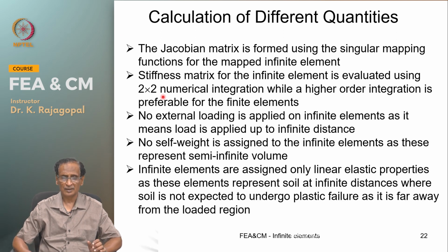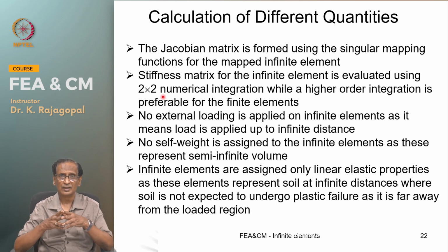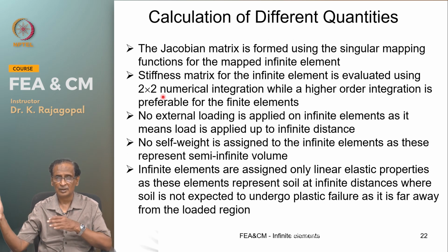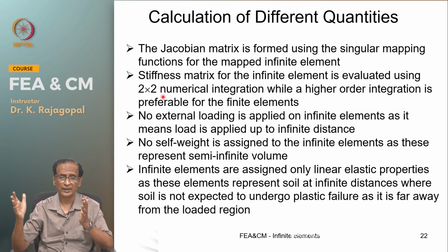And another precaution that we need to take is, we should not allow any failure to take place within the infinite element. If any plastic failure takes place, that means that the soil up to some infinite distance has failed.